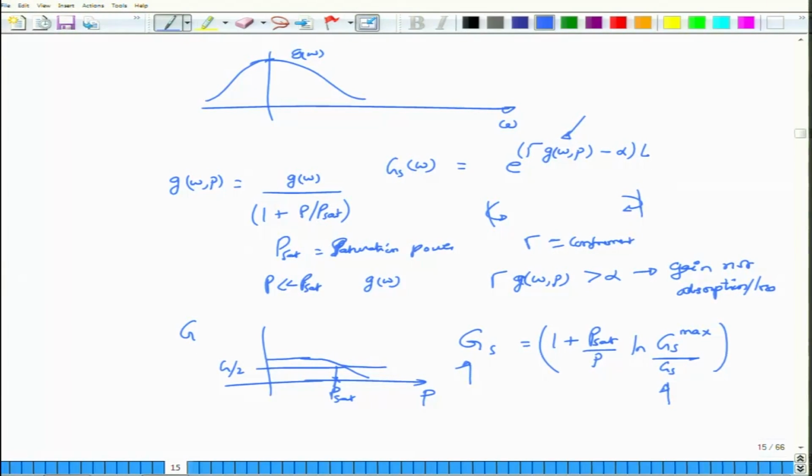The actual gain depends on cavity design, reflectivities, the stray light that enters into it, the packaging. All those things have to be optimized if you want to create a good amplifier, and of course you also have to do some sort of optimization if you want to create good lasers. Okay. So, this was about semiconductor optical amplifiers.